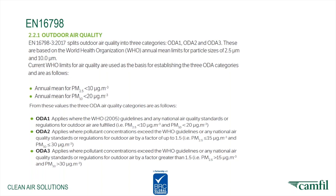From these values, the 3 ODA air quality categories are as follows. ODA 1 applies where the WHO 2005 guideline, and any national air quality standards or regulations for outdoor air, are fulfilled. ODA 2 applies where pollutant concentrations exceed the WHO guidelines or any national air quality standards or regulations for outdoor air by a factor of 1.5. ODA 3 applies where pollutant concentrations exceed the WHO guidelines or any national air quality standards or regulations for outdoor air by a factor greater than 1.5.